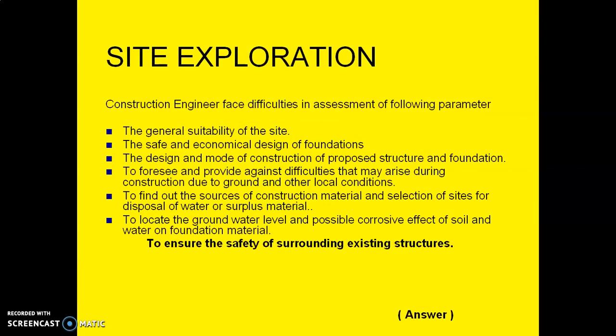The knowledge about the site plays a vital role in the safe and economical development of a site. Public building officials require soil data together with the recommendation of a geotechnical consultant prior to the issuance of a building permit. Elimination of site exploration leads to false economy of redesigning the structure.